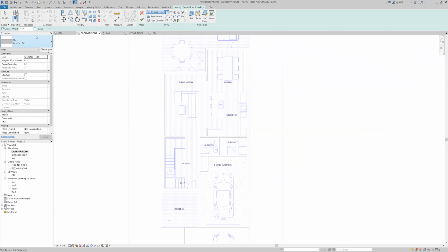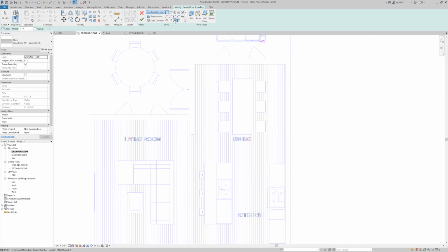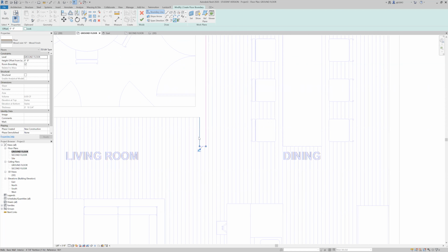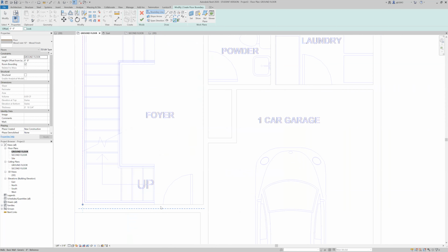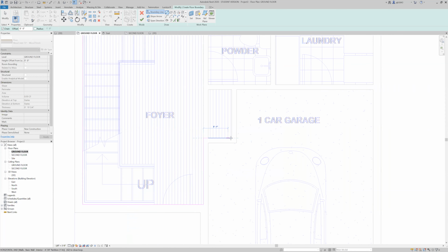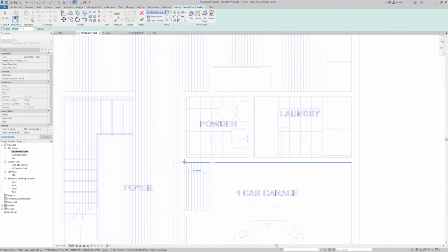So the easiest way to do this, we'll just use the wood joist 10-inch wood finish, as this is what we use in the example project that we showed you to start with. So in sketch mode, you can again just trace it, or you can use pick lines to get these interior wall locations. This is usually a lot faster and a lot more accurate to use this tool, as it prevents you from bringing human error into it so much, where you might not perfectly align the line to the wall.